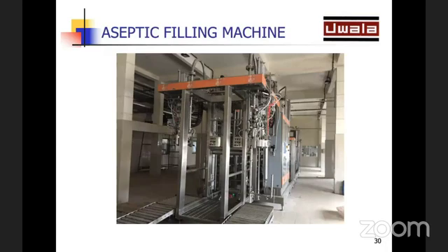This is what an aseptic filling machine would look like. As I had mentioned earlier, if you are doing aseptic filling, you don't need to add any preservatives. And how are we able to achieve that? We are able to achieve that because the product always remains sterilized. Before filling, there is a sterilizer attached to this machine. We sterilize the product, that is, we clean the product from all microorganisms by heating it up to 90 degrees centigrade. And then we don't even allow air to enter into the system.